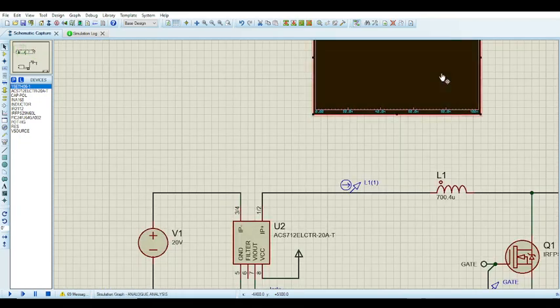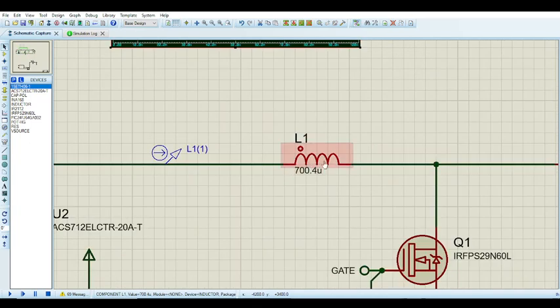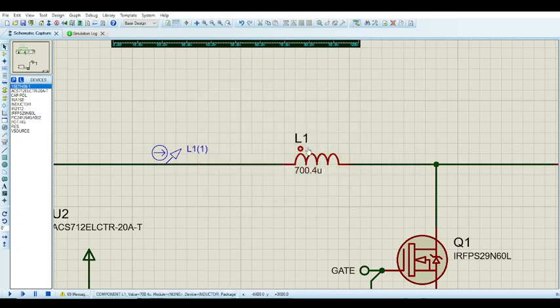Obviously, you're going to be checking on your actual system. And one thing to note with the hardware, for average current mode control, your inductor is in CCM constantly. So for your inductor to be in CCM, you have to ensure that this value is sufficiently large. You can't have 60 microhenries here. This is not like constant voltage on the output only.